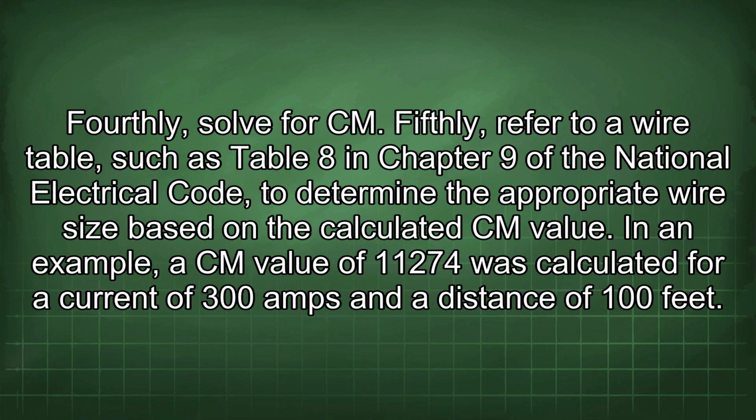Fourthly, solve for Cm. Fifthly, refer to a wire table, such as Table 8 in Chapter 9 of the National Electrical Code, to determine the appropriate wire size based on the calculated Cm value.